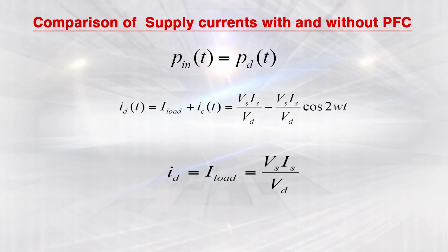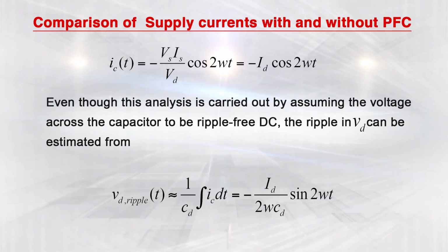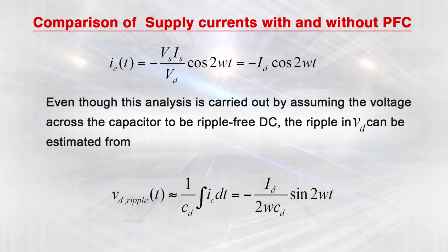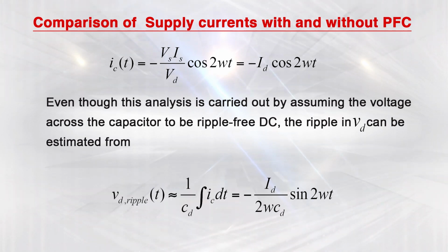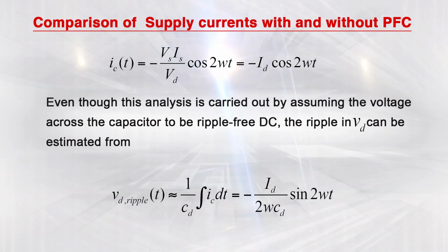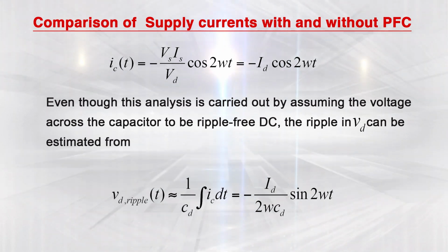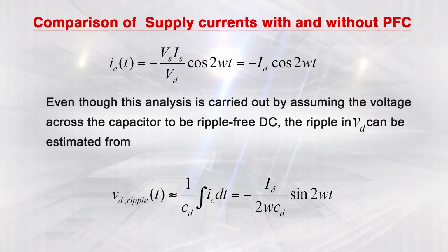It has to be addressed, because in the case of a single phase supply, the instantaneous power oscillates at double the fundamental frequency. So, these ripples have to be addressed, and up to 10 to 15% these ripples are allowed, otherwise we need to redesign our system if the ripple is more than 10% or so. This way we can get the various equations for ripple and these powers.